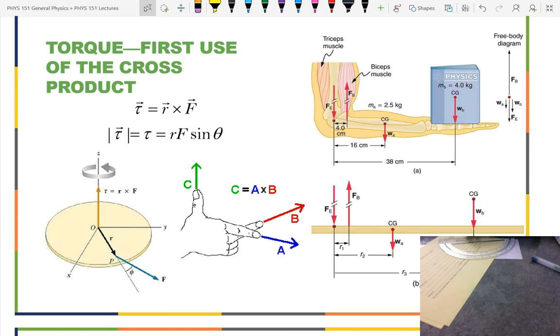And so, unless you go to some excited... Okay, so the fluorine is really bad. The fluorine will tear up your normal rubber gaskets in your regulators. And so they don't want you to use the regulator that you use for helium on a fluorine tank, because it will erode that rubber gasket, and then you'll have fluorine fill the room, and people will die.